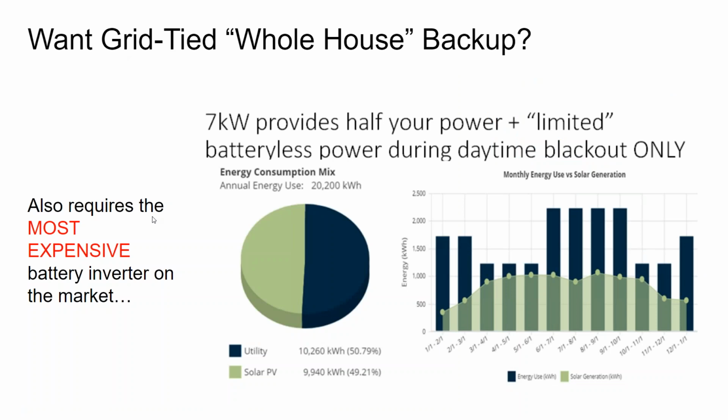And so, grid-tied solar with backup batteries for power outages is a little bit less satisfactory than you would think. The storage inverter goes up to 7 kilowatts, and that can only get about half your power. The critical load panel is even smaller than that.